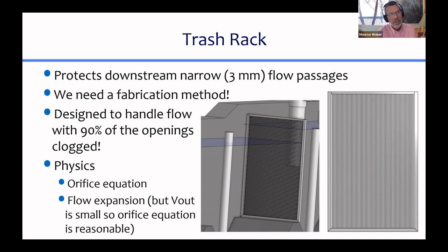And I'm wondering, given what we talked about lately, do you see the connection? If the trash rack doesn't have very much open area, then why does that make the head loss higher? And would you be able to tell me what the head loss through the trash rack might scale with? I think I'm going to ask you the question.